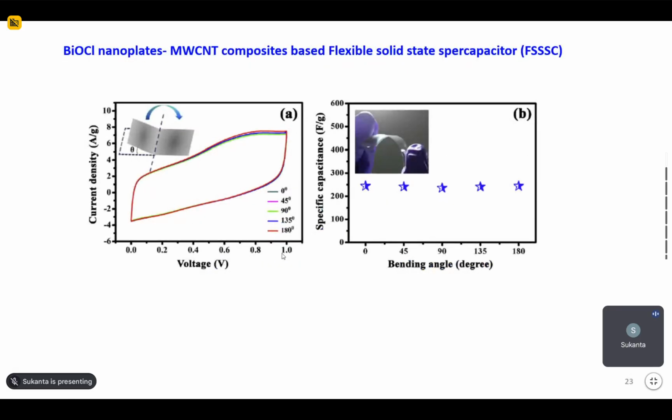So till now, we have seen which types of materials can be useful for preparing supercapacitor electrodes. For an electric double layer capacitor, we generally use carbon materials like carbon nanotube, activated carbon, or carbon black. To improve the properties, we can use pseudocapacitance materials like molybdenum oxide and other oxide materials, and their nanostructures like the 2-dimensional nanosheets that I have shown you, and how to prepare a flexible supercapacitor on top of a flexible substrate or as a freestanding film.